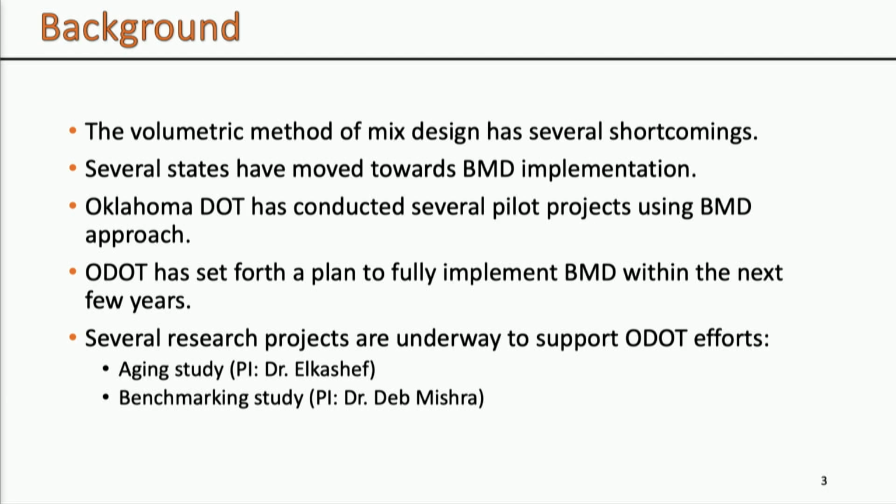And this has been okay until people started looking into recycled materials, new technologies, different binder sources, new additives, and then they started to realize that volumetrics is not going to be sufficient to be able to characterize these new mixes. So this is where BMD started to come into play. BMD is just a term which means balanced mix design. So we're just trying to look at balancing the mix so that we get good cracking performance and good rutting performance. And if you're not into asphalt, the challenge that we always get is we want to add more binder to get more durability, more ductility, but with the addition of more binder, if we're not too careful, we might end up making our mix rutting susceptible. So that's where the balance needs to come in.